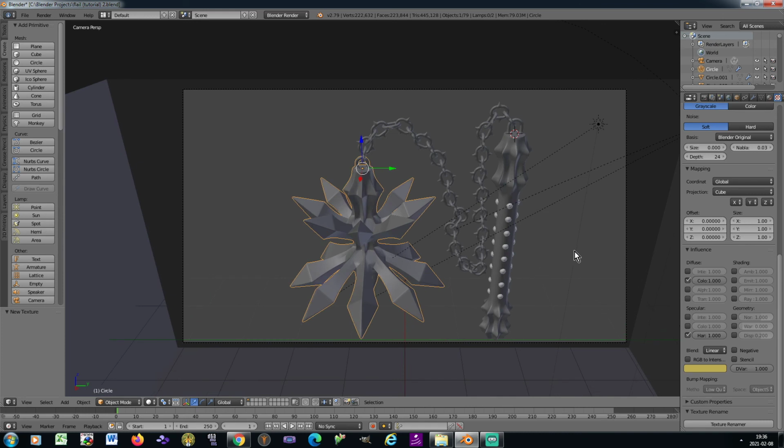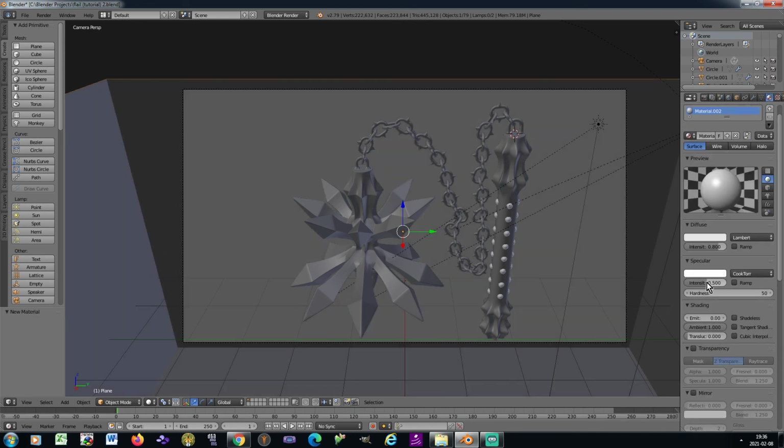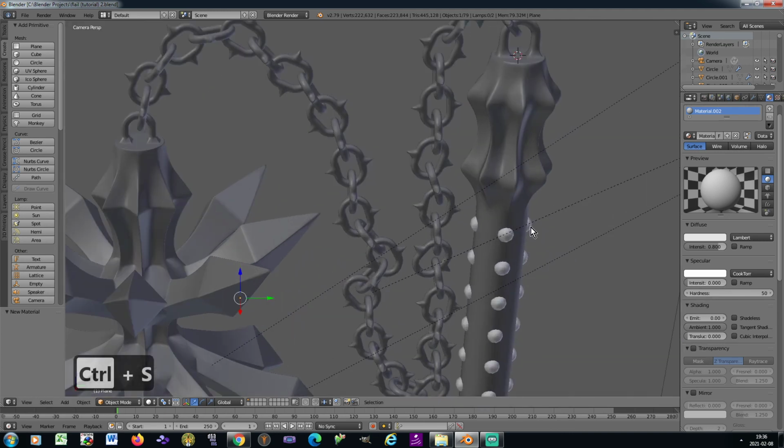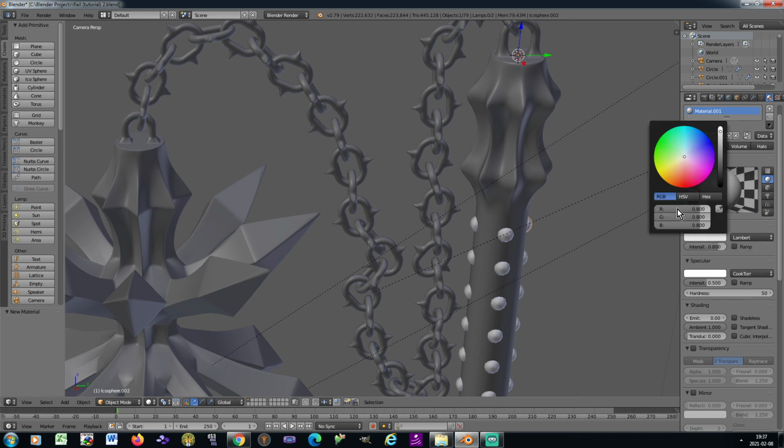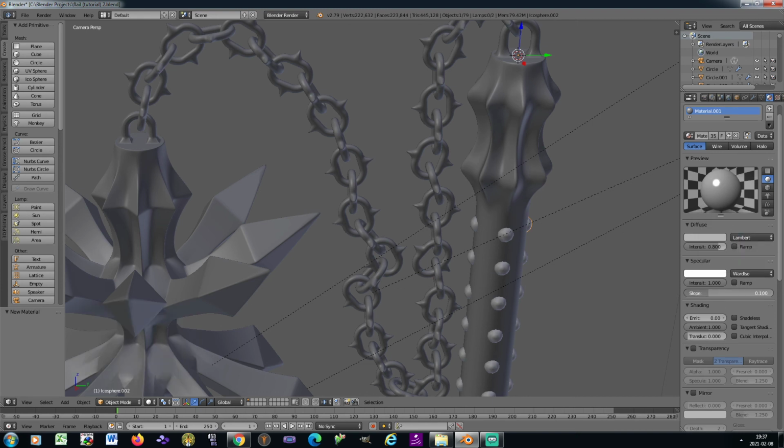Now let's add a material to the box. Set specular intensity to 0. Very fast. Now let's add a material for the mirroring spheres. Diffuse color, all three at 0.47. Specular intensity 1. It's gonna be a Ward Iso shader model with the slope 0.15.